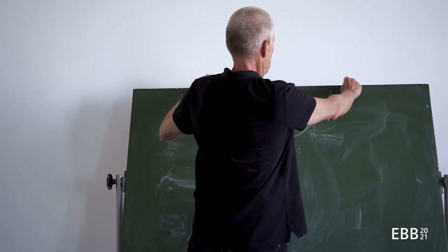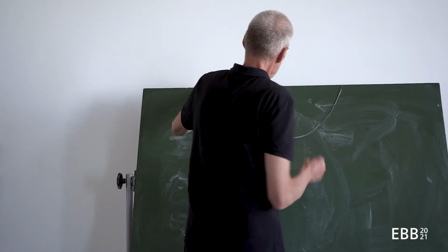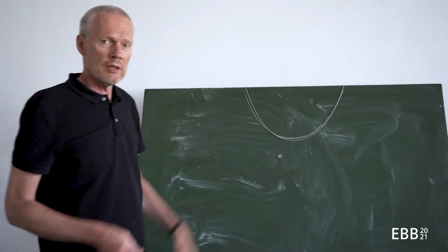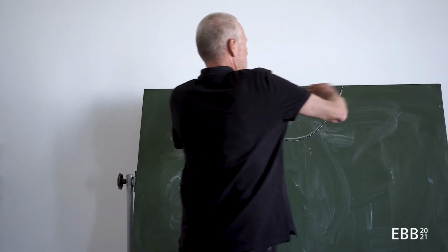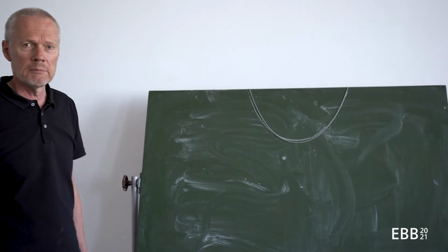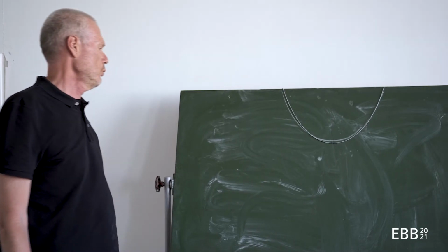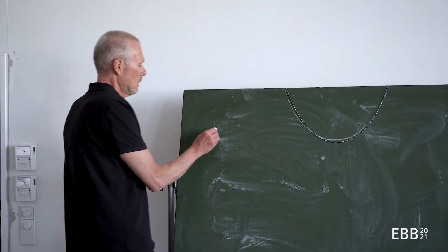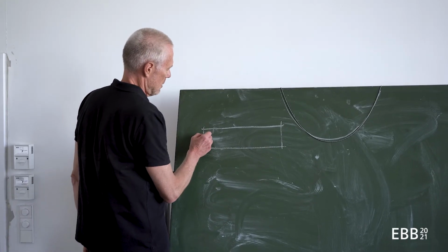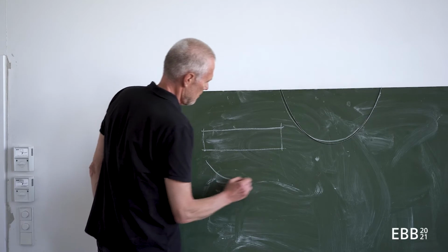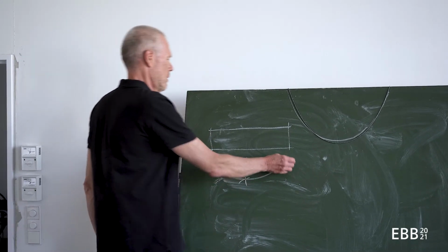You will see this when I push it out. It will try to get back into the original form, which is due to friction here on the upper part. The more horizontal I make it, the bigger this horizontal load here becomes. And if I translate this to a beam, I could see that the beam has a moment diagram as well, which is maximum in the middle and it becomes zero at the end.